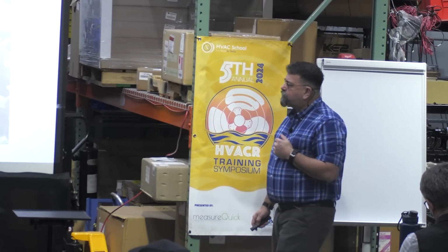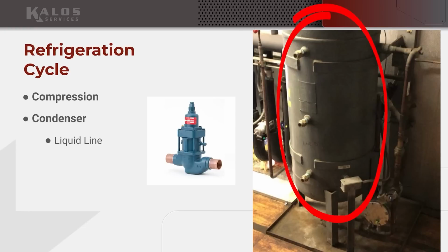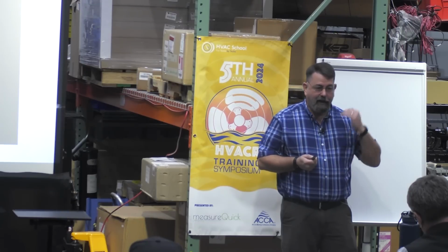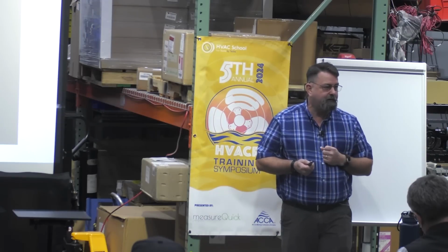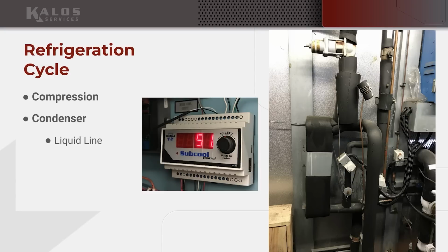All right, so another piece that is going to be different. I told you we can't adjust our charge and cause subcooling. Because my receiver has got liquid and vapor in it, it's at saturation, right? So all that subcooling I would have done in my condenser, lost, right? I'm at saturation. Can't be superheated, can't be subcooled. I have vapor and liquid present. I'm at my PT chart. Right? Does that make sense? But we probably want a little bit of subcooling.